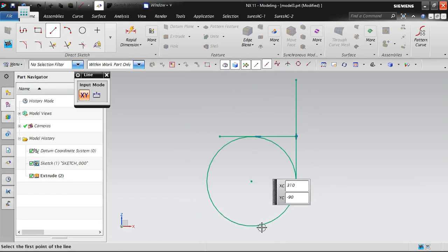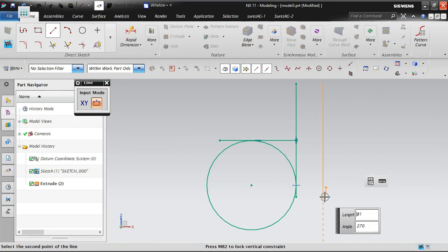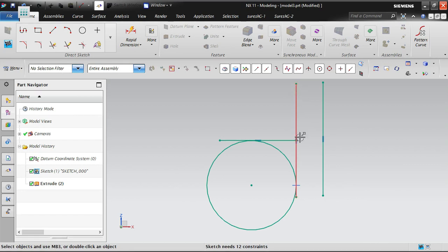For example, now I'm going to create one line here, like this. So this takes a vertical line. This didn't take any parallel or perpendicular or anything. See, I created it near this line only, but it is not taking any parallel, it is taking only vertical. Why? Because the first preference is horizontal and vertical. Later, whatever constraints you want, you can give accordingly. Okay, so this is what inferred constraint is.